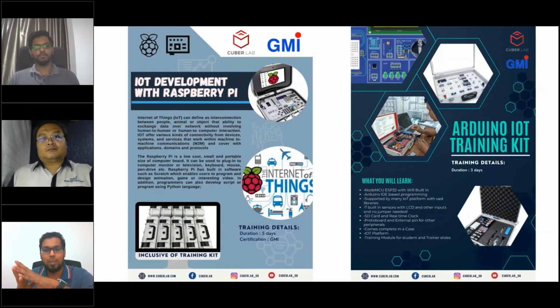For this type of company, the 6-axis robot is better because you can just reprogram it to do different tasks easily, rather than being fixed with a linear robot, which has limitations, while a 6-axis robot can do much more. So after 6 months or 3 months of assembling this product, when a new product comes in, you can just reprogram the robot, change the end effector, and use it. So it all depends on your application.